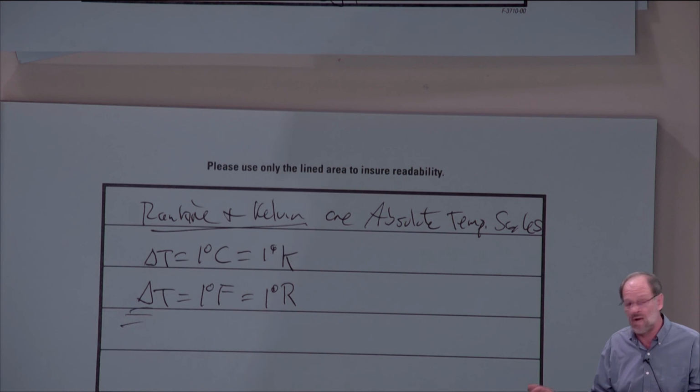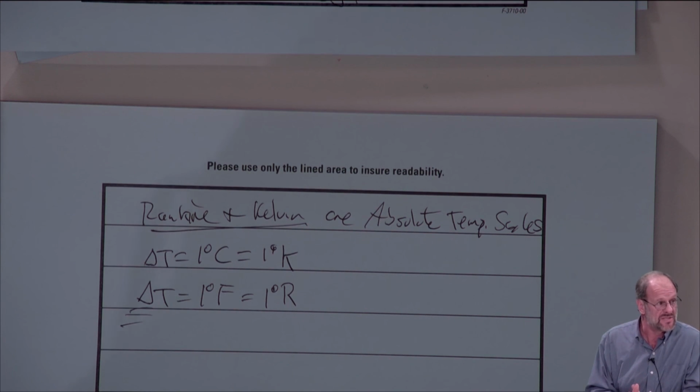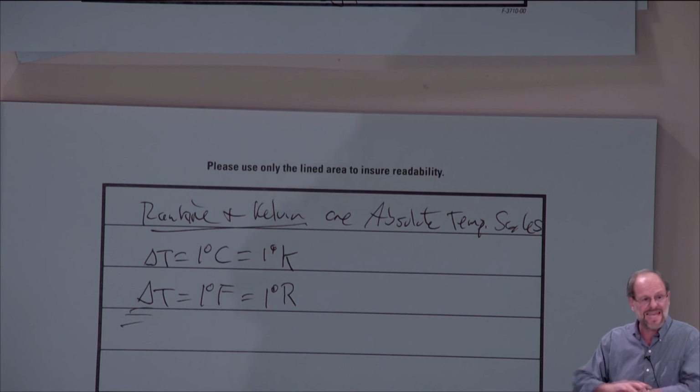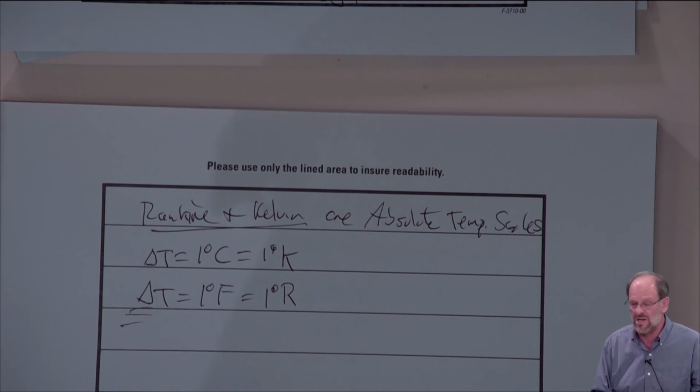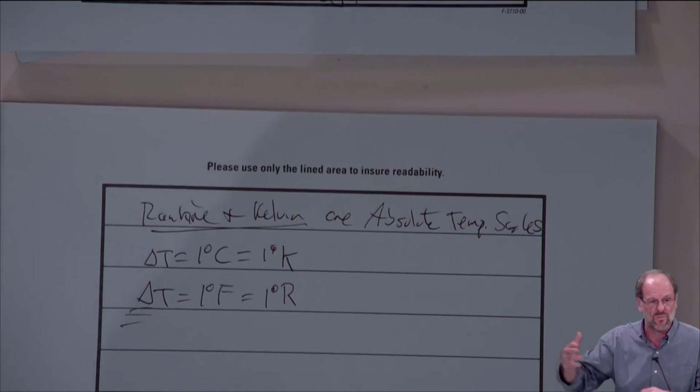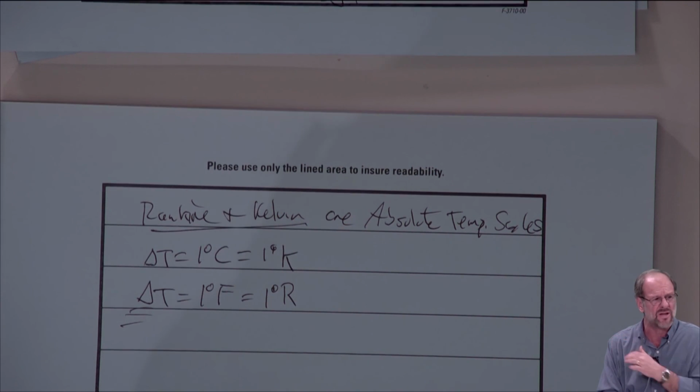It's also a measurable property. So like pressure, these are going to be the two properties that we're going to use for practically every single problem. Remember, if we have two independent intensive properties, that sets the state for us. We can go and find any other property knowing any two independent intensive properties. So most of the time, temperature and pressure are going to be two of the intensive properties that we're going to have available to us. We'll use those to find other properties, and we'll be talking more about that either by the end of the week or next week. Yes?